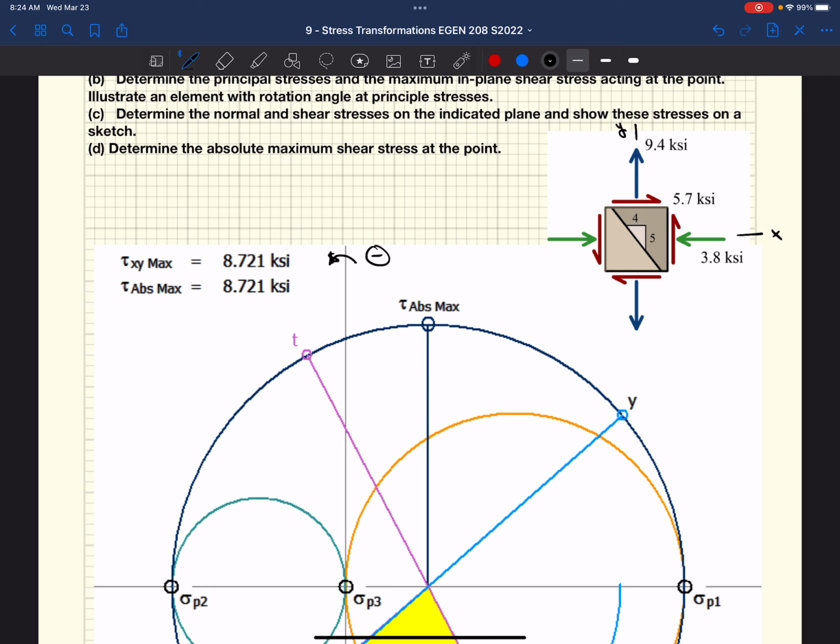When we go to plot a Mohr circle, it's negative, right? It's on the left-hand side down here, just as they show. Also with the shear stress, we know the convention for shear stress. If it's on the positive face acting in the positive direction, it's a positive shear stress. Or we could use the right-hand rule, and if we looked at these stresses on the X faces, it's trying to rotate our block counterclockwise. So it's on the positive face, positive direction. It's a positive shear stress.